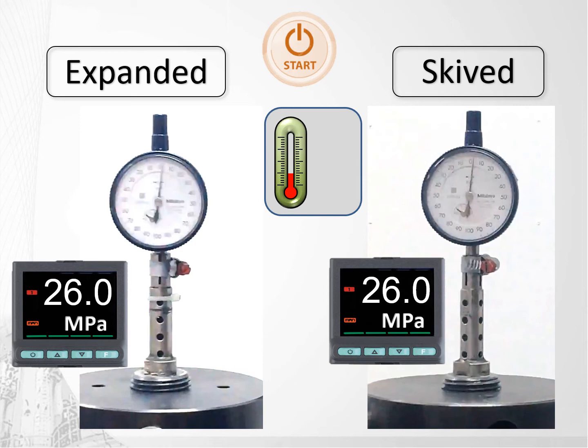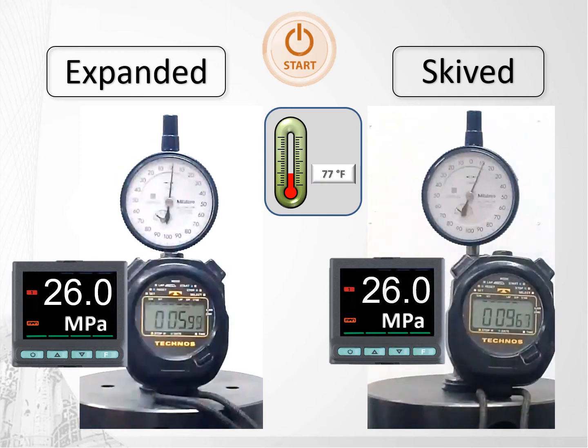The gaskets were installed with 26 megapascal and allowed to relax for 1 hour. The rig was then heated up to 302 F, which is 150 degrees C, for another hour. So let's see what happens.